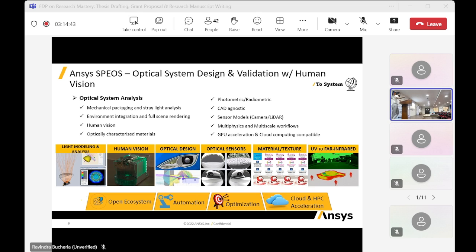In the older days, in school, whenever we talked about the refractive index of water, it was 1.33, but it is actually a function of a lot of things. Refractive index is a function of temperature, of wavelength, of frequency, of voltage. So there are different models, and based on that, you can import your own models and analyze them well.